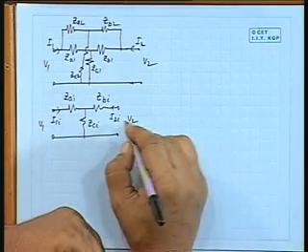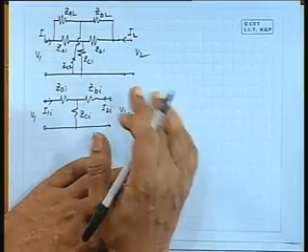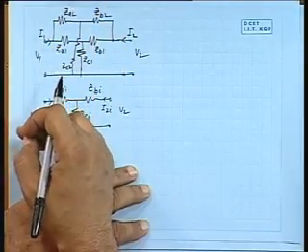Therefore, from here you write the y parameter values. You have to just go for star to delta transformation, or by the earlier method, applying short circuits, you can write in terms of these impedances. Once you know ZAi, ZBi, ZCi, you substitute the exact values for the two cases, and then add them together.